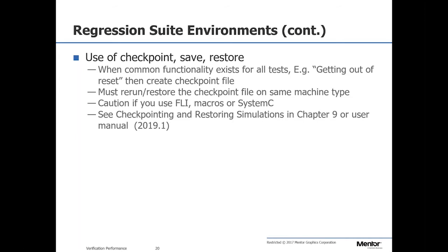That way, if 3.5 days into a 5-day simulation you get a lightning strike and the power goes down and your computer shuts down, you can restore back to the last checkpoint and only have to simulate for another 1.5 days versus restarting your 5-day simulation. So that's the easiest use for checkpoint and restore.